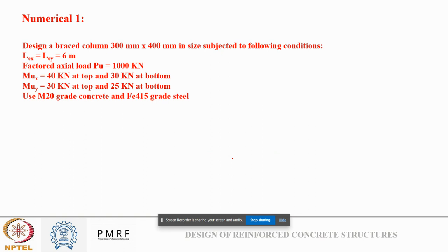I will just wait for a couple of minutes. Just try to recap how the design is done, how with external moment we define 0.4 M1 plus 0.6 M2, and how we actually take external moment into account. Just think about what we have discussed in the NPTEL classes also, and the live session that we covered last week, and then we'll see the solution after a couple of minutes.